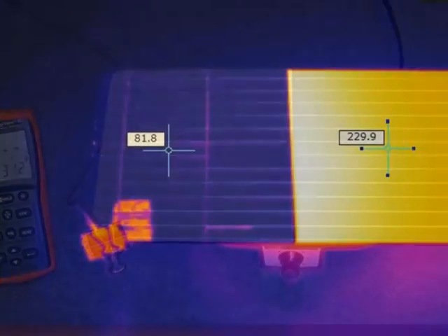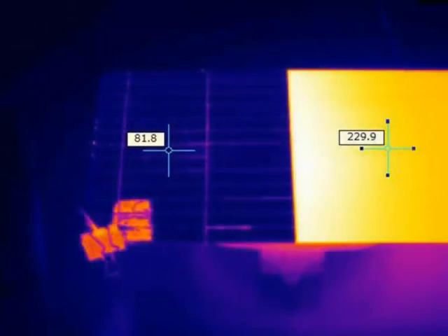Yet if we look at the IR image of the shiny plate, the reading says 82 degrees Fahrenheit. The anodized section of the plate reads 230 degrees Fahrenheit with the infrared camera. If we were only looking at the shiny plate, we would have a totally incorrect conclusion about the true temperature. The reason: shiny metals have low emissivities and do not emit infrared radiation well.